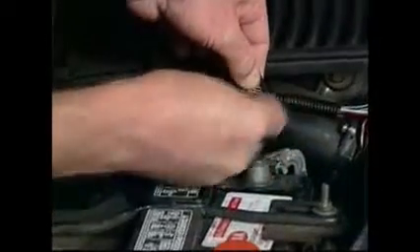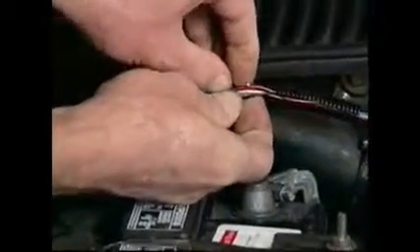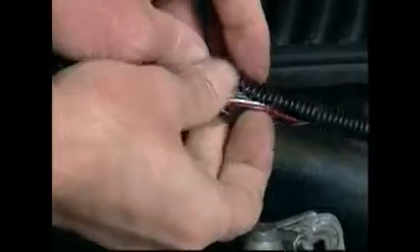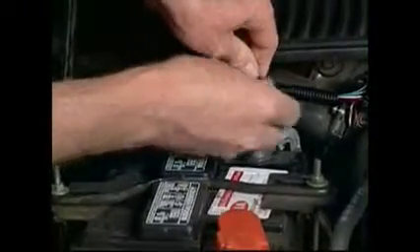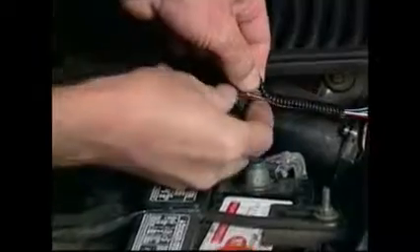When replacing a section of wire, it is imperative that you always use the same gauge wire in the repair. Think of Ohm's law. If you use a larger wire in the repair, the resistance of the circuit will be lowered and a higher than normal current flow will result. Using a thinner wire will increase circuit resistance and reduce current flow.